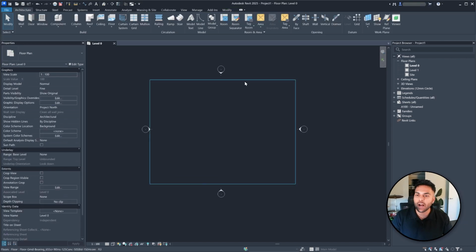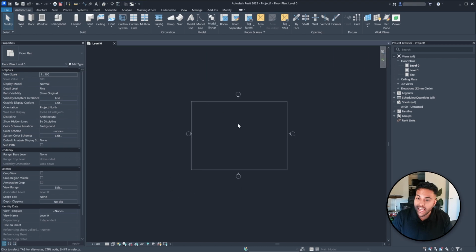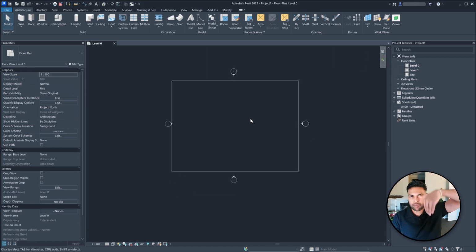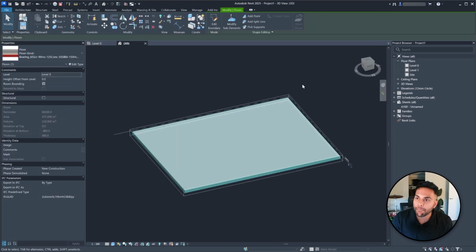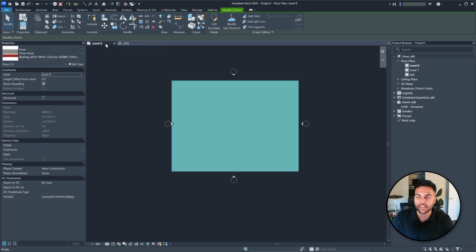What you'll notice is that you can't actually move and see this in 3D. This is 2D, okay? Bird's eye view. You're looking at it from the top. If you want to go to 3D, you have to click this and click BX. If you click BX or you select it and select this section box, you'll actually go to the 3D view. And you'll see that it's created, it's like Google Chrome, an additional tab over here. So it says 3D, and then this is your 2D.